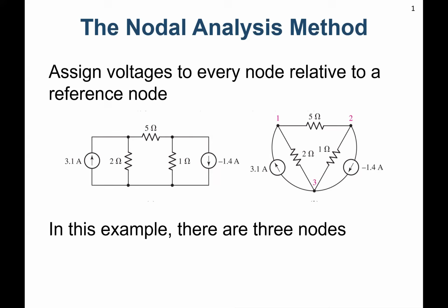We're starting a new module today, which is some circuit analysis. And we've done a bunch of it already, but we're going to formalize it a little more, or take a slightly different approach maybe than what you may have seen in the past, once the screen comes on. There we go. So nodal analysis is just KCL, which is the sum of the currents into the node equals the sum of the currents out of the node.